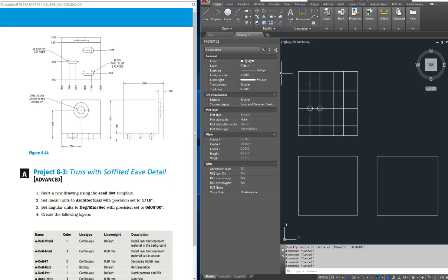So now I need to draw these two larger holes here. So I'm going to draw a circle, and I'm going to put it on that intersection, and it says right here it has a radius of 0.085. Okay, it defaults to wanting to draw a radius, so I'm going to say 0.085, enter. And since I did that once, all I got to do is hit circle, pick my center point, and I don't have to enter it again, and that ought to go really quick for you.